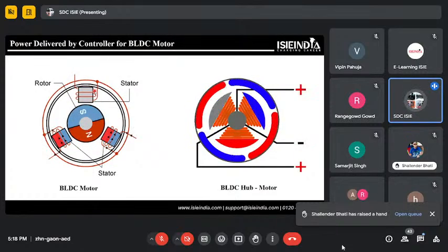So to run that motor highly efficiently, when to come in the forward connection, when to turn on the power supply, when to flip the power supply, all these are getting responses with the help of hall effect sensors which are present inside this. And in the motor, the hall effect sensor we use is called a bipolar hall effect sensor. These bipolar hall effect sensors are capable of detecting the position for a north field as well as a south magnetic field, and as per that only they give the command to the controller. And each BLDC motor has three bipolar hall effect sensors, right?